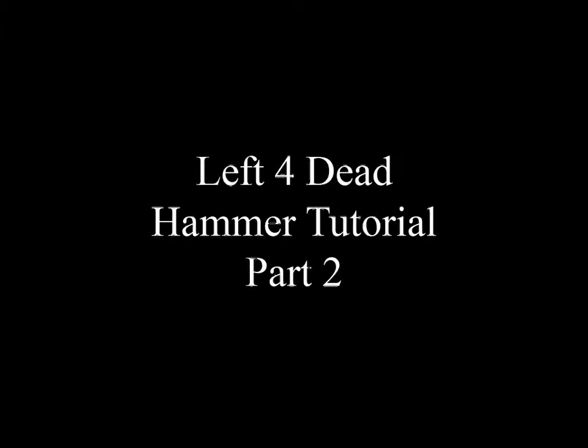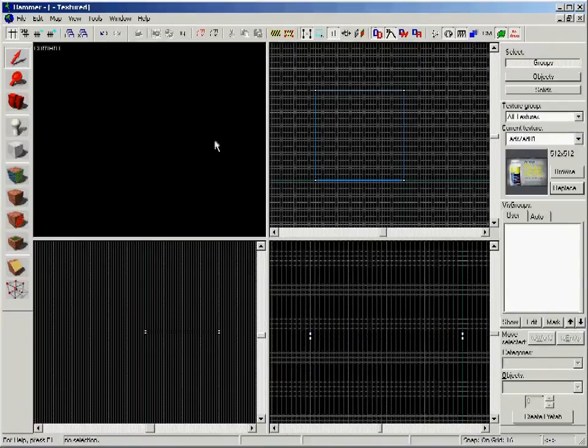Welcome back to the Left 4 Dead Hammer tutorial. You should now have a brush that measures 512 units wide, 512 units long, and 16 units high. To get yourself oriented and see our new floor, you can use the 3D view pane.